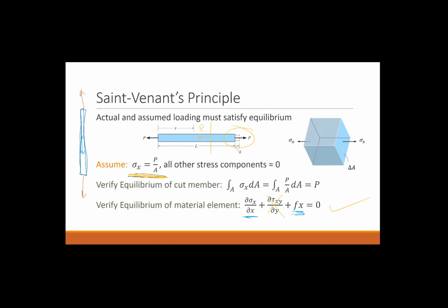Okay, so think about how gravity acts. If I am looking at this point here at the bottom, how much force is pulling down on that point due to gravity? How much of the bar is below that point? Zero. So there's no force pulling down on it as a result of gravity. What if I look at this point at the top? Now how much force do I have? So you have the whole weight.